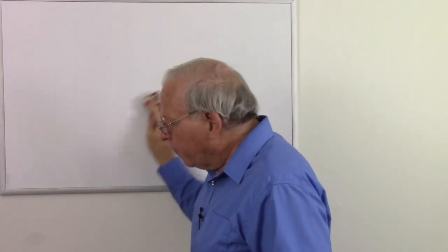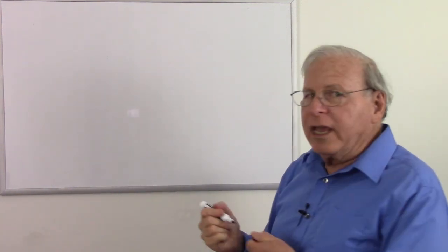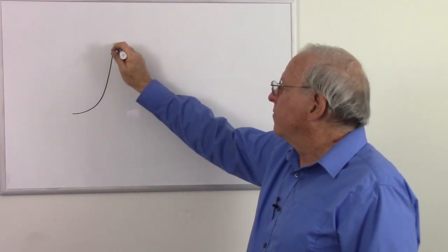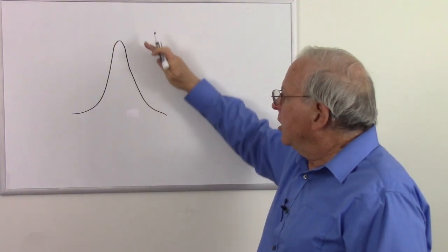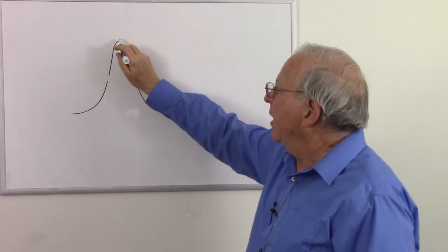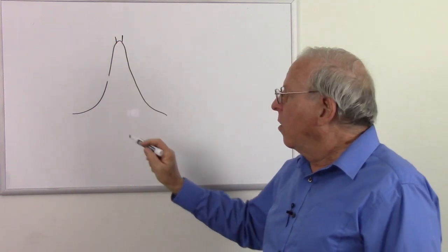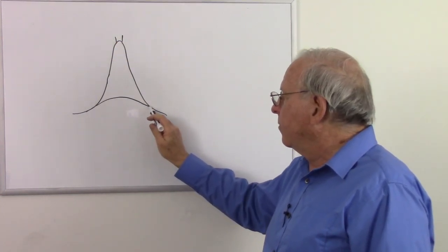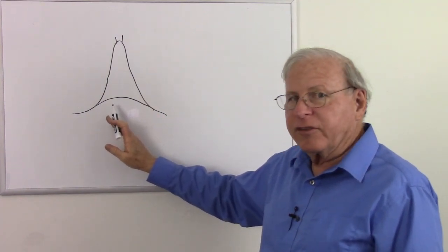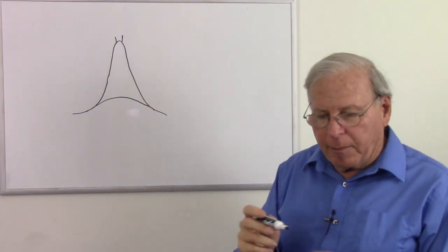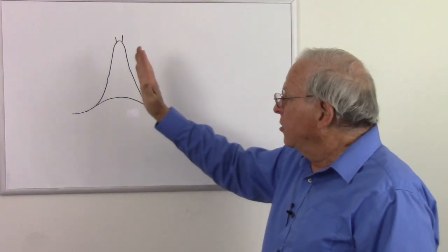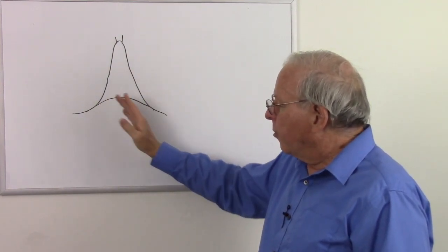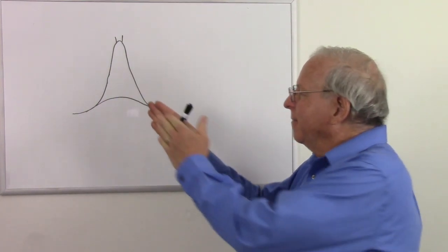Because so far we've looked at how we can tweak the response. We can have a filter with low resistance and get a very high Q, for nice steep sides and a narrow bandwidth. Or we can add some resistance and bring that down and get some more bandwidth. We don't have the steep sides. And this can be problematic if we need to have a sharp cutoff with a broad band. Because as you can see, if we broaden the band, we get less cutoff.